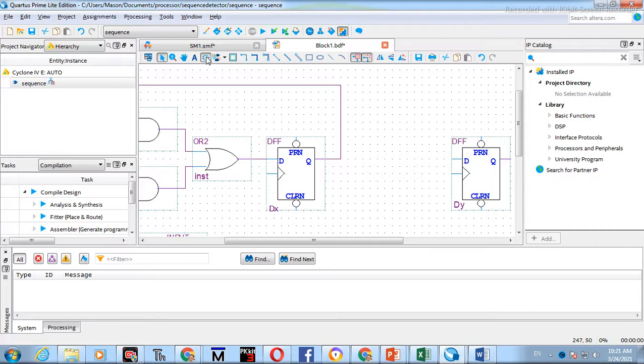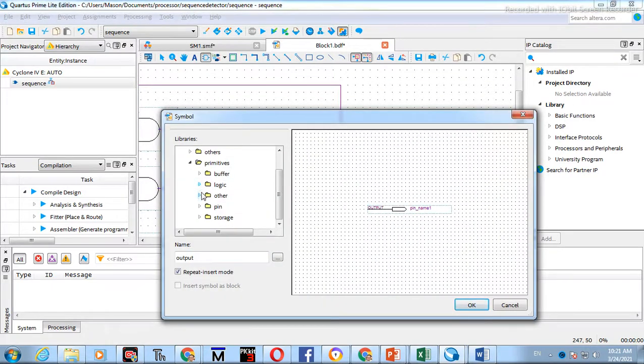After that we can choose the AND gate, the logic gate. The logic gate is here, so choose the AND gate. The 2 means there are two inputs. If we have three inputs, we choose the AND3. That will be three inputs. And then we have a NOT gate, and we have an OR gate. So choose the OR gate and the NOT gate here. This is a NOT gate.